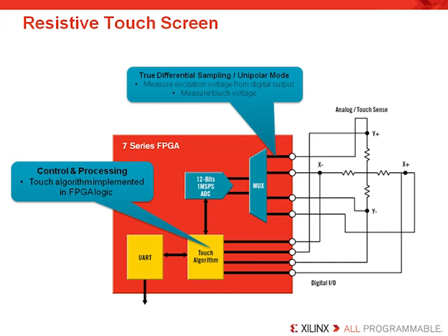Using the XADC block, the Xilinx devices can directly measure sensor voltage. The FPGA then processes the samples, compares the values to the thresholds, and manages the touch or touches. As shown in the figure, only a small amount of FPGA fabric resources are required to do this. Moreover, even the smallest, lowest cost Artix-7 device has plenty of resources remaining for many additional functions.